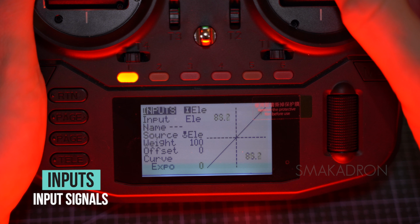As the Expo percentage increases, the sensitivity curve becomes flatter near the center, which reduces the stick's sensitivity in this range. As the Expo percentage decreases, the curve becomes steeper near the center, which increases the stick's sensitivity in this range. At a value of 0%, the sensitivity curve is linear, which means uniform sensitivity throughout the entire range of stick movement.